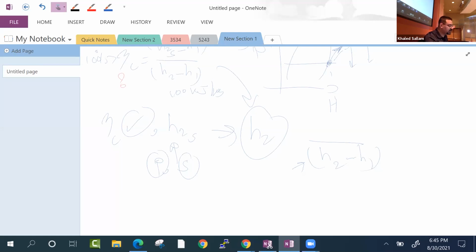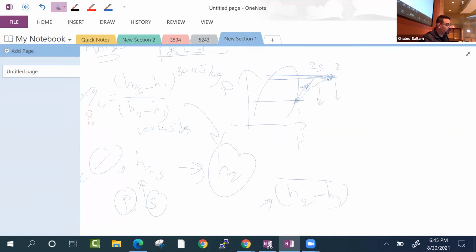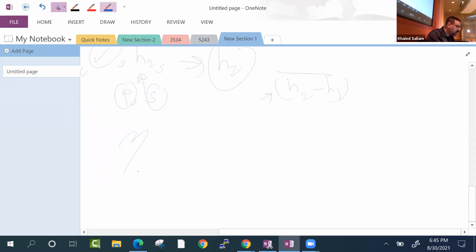So for example, the project was about a vapor compression refrigeration cycle, and you are trying to figure out what is the COP as I go to different temperatures, or designing a refrigeration cycle that works between those two temperatures. And you did everything based on isentropic expansion and compression and everything. Then at the end, you would basically say, now let me assume an ETA compressor that is practical, and let me see how does this change my COP, right?